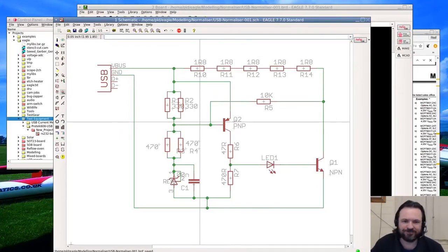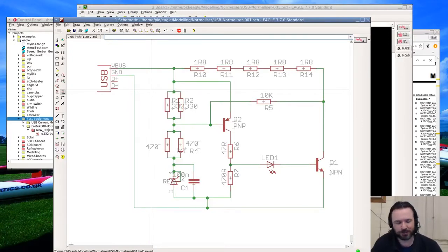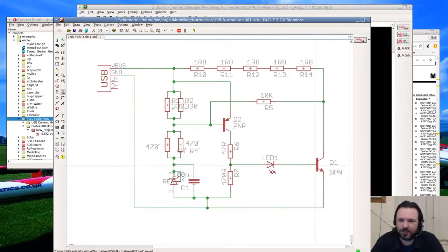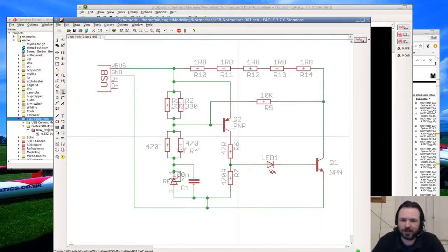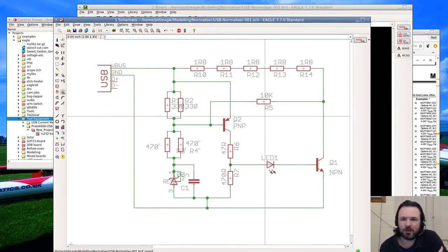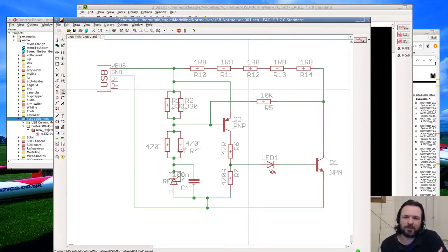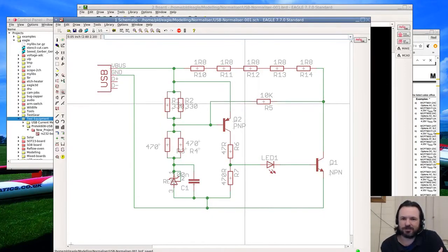Yeah, that was a long time ago I did this circuit. And like I said, the only reason I keep it is because it's so cheap. The downside is every time I get a new batch of these transistors, I have to adjust these values to suit the new base emitter voltages. Yeah, we do still get some oscillation even with this feedback hysteresis. It's sort of a feature. It makes it blink when it gets close to the end. I could make it bigger and force it, but there's no real point.